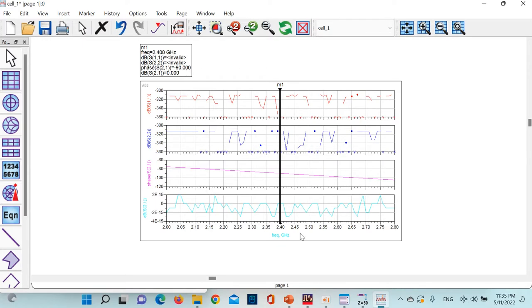Okay, and my S21 in dB, because the line is ideal, it makes sense that you don't have any loss, right? Tangent D is 0, so it's showing 0. And the other ones, because there are some breaks here, it's so good that it's showing just invalid, but you can see that it's better than minus 300.